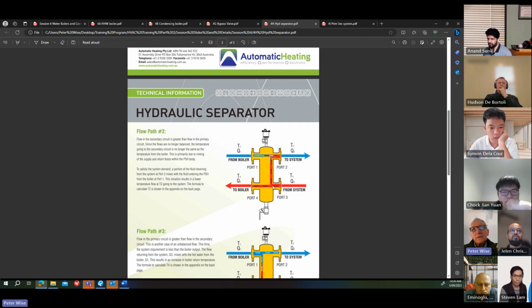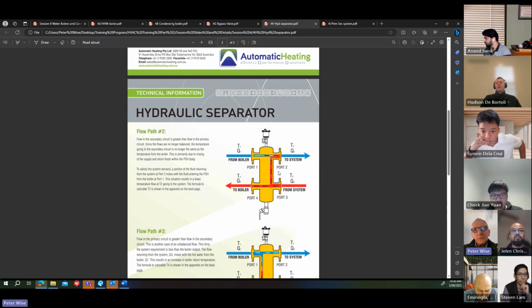From the secondary side, it's coming back out to the field without returning to the boiler. And this is typical primary secondary system operation. And then the controls have to compensate to provide the additional hot water that's being requested from the secondary side. So this is where staging of the boilers will come into play.